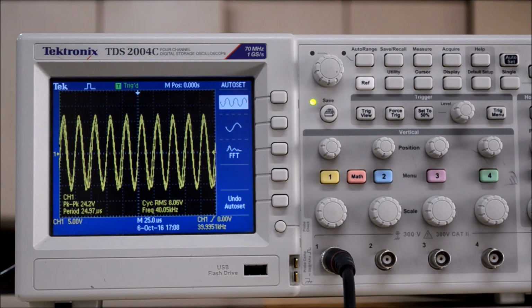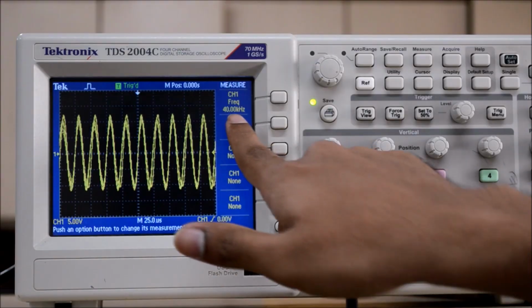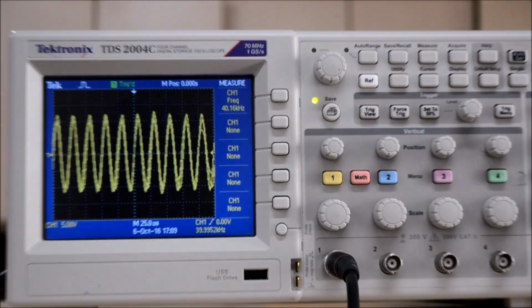Now we observed that the carrier frequency was 20 kHz. We also saw in the equation that after squaring we use the trigonometric identity and obtain the equation as 1/2 plus 1/2 cos of 2 into 2πfct. That is, we should get twice the frequency of carrier. Now let's check whether we are getting 40 kHz. We'll press the measure button here and we'll observe the frequency here. So we are getting 40 kHz as the output frequency of bandpass filter.